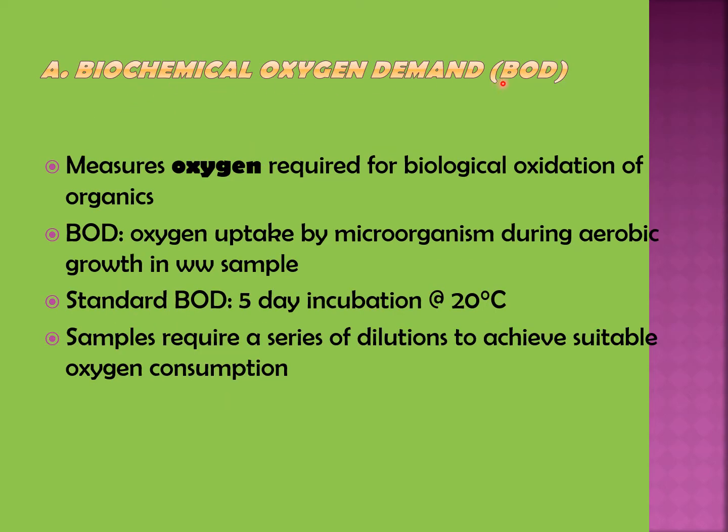Biochemical oxygen demand, BOD, is the amount of oxygen demanded by a wastewater sample. So we can say BOD is the measure of oxygen required for biological oxidation of organics. In another way, we can say BOD is the oxygen uptake by microorganisms during aerobic growth in a wastewater sample.